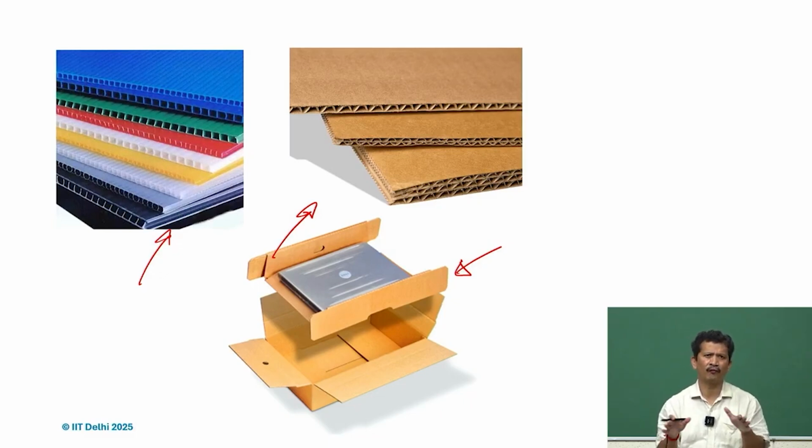So, it can be wrapped around, and these days you also see a lot of origami kind of structures. By folding, we try to get stiffness and rigidity, and it's very good under impact loading also. So, it's safe. We can see a lot of package design these days. Again, a very good application, and it's completely based on stiffness-based design.